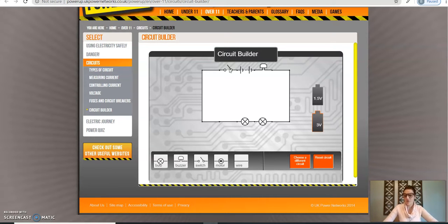This is what is unique about a series circuit. There is only one path of energy to flow around the wire. So if any point on that circuit is broken or open, if a switch is open, not a single object on that wire will work.